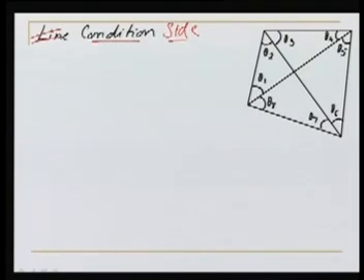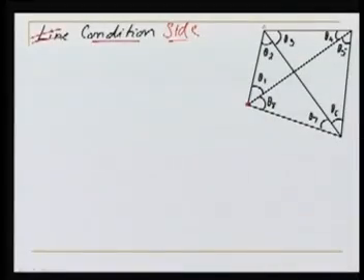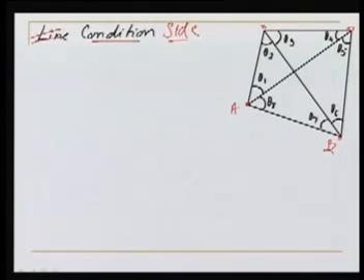Now what that side condition is, the side condition takes into account the length, or rather the figure is closed, because you know this figure needs to be a closed figure as it is in the field. In the field we have 4 stations, and those 4 stations, they form a closed figure. So we have to ensure that our angles are such that they form a closed figure. Now how do we ensure that? Let us say it is A, B, C and D. That's our quadrilateral.